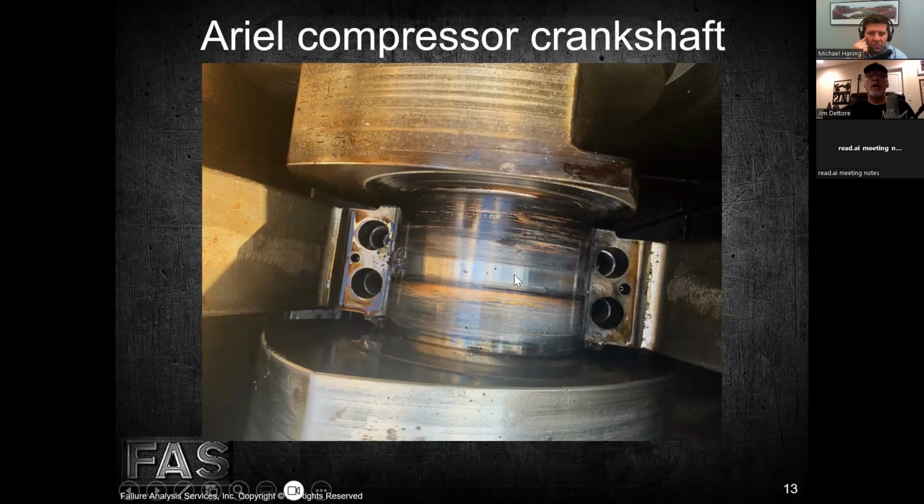But we've had no contact in the center because that's where our oiling groove is in our bearing. But you can still see the debris that's pulled off of the bearing, collecting in these areas here. And we're starting to generate some considerable thrusting, and you can see the temper colors in the crankshaft counterweight as well. Now is this a clearance issue, because it doesn't go all the way across and you've got that selected however many inches that is of really clear wear?